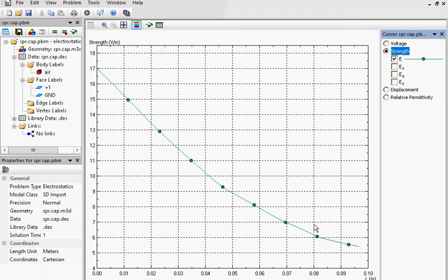But what if we didn't know the analytical solution in advance? What should we do then? How to make sure that the solution is accurate? Well, that's easy. You just build a denser mesh and compare the results.